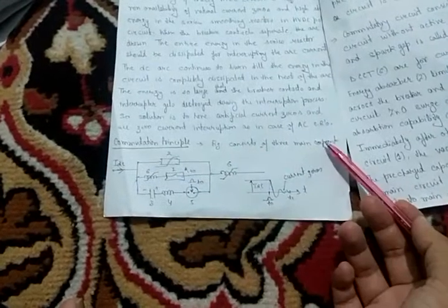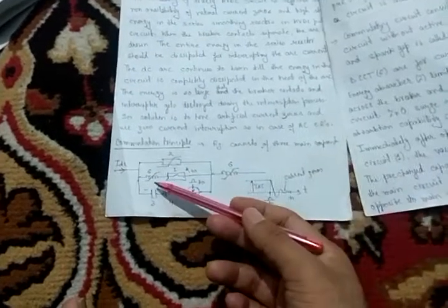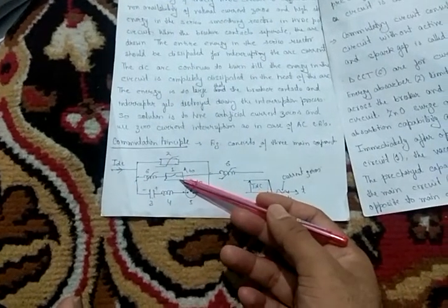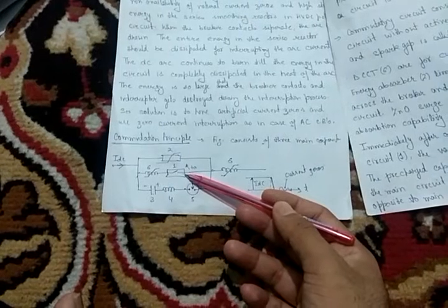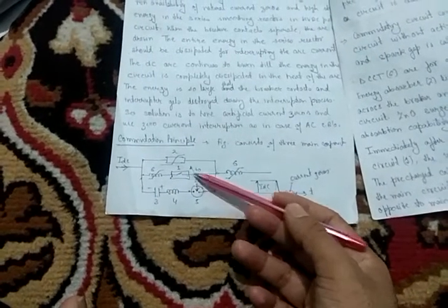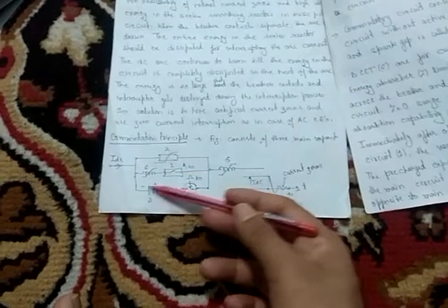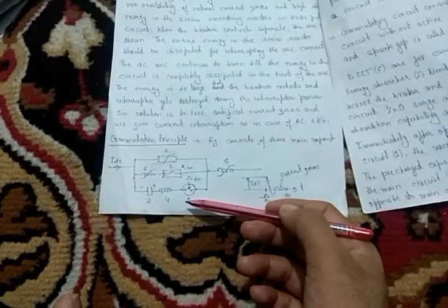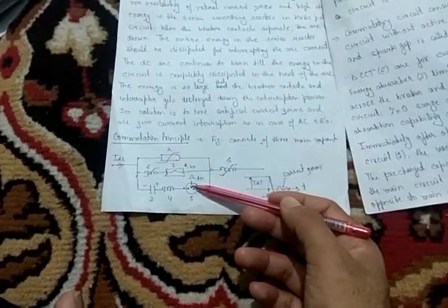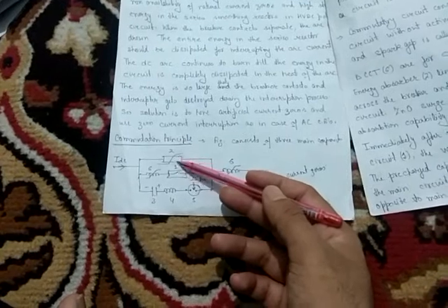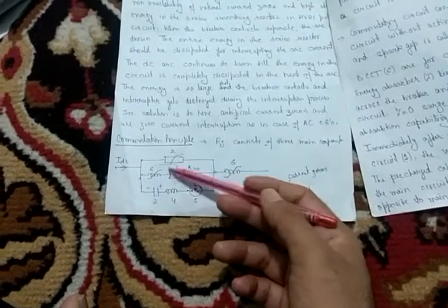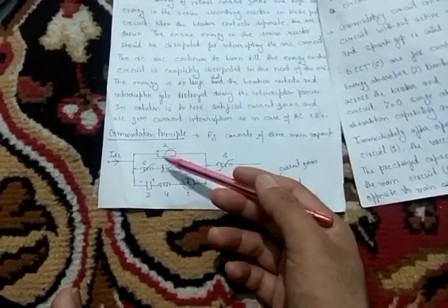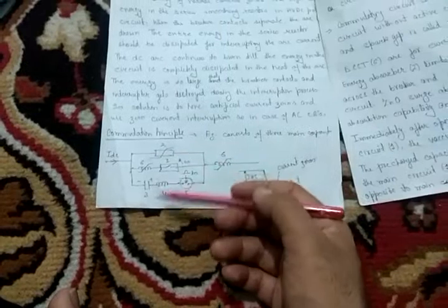This figure consists of 3 main components. The first is the main circuit, which means 1 and 6. It consists of the main circuit breaker, which carries current IDC, and commutates the current to the commutating circuit. This is the commutating circuit down here. The commutating circuit consists of an inductor, a capacitor, and this switch. The second is the current energy dissipation circuit, which absorbs the energy. This circuit is made of a zinc oxide arrestor, which absorbs some of the energy of the system.